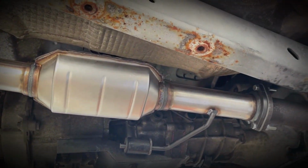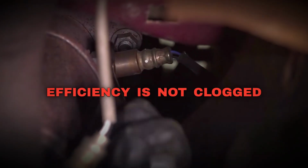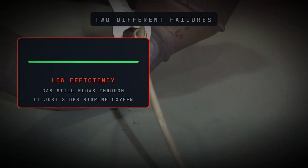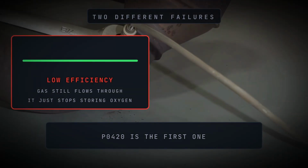Check 5. Confirm catalyst performance. P0420 is an efficiency code. It does not automatically mean the converter is clogged. Those are different failure conditions. A converter may allow exhaust to flow normally, but no longer store oxygen or process emissions well enough to pass the monitor. The vehicle may drive normally while the check engine light remains on.